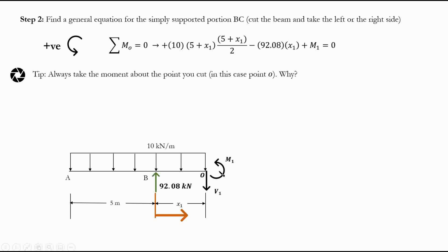When you cut, the convention is that the moment is always in the direction that creates compression at the top and tension at the bottom. And shear is always in a clockwise turning sense, so this V1 is turning clockwise. I'm not going to go over that, but you can find it. This is going to be very useful when we are drawing bending moment diagrams, and it's good to be consistent and draw them in these directions, in case you're wondering why I drew this in this direction.